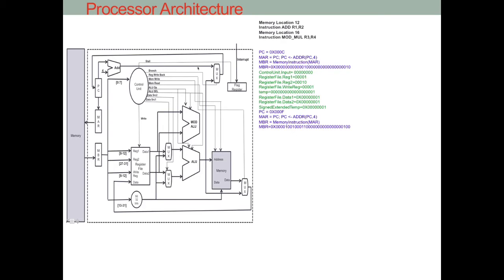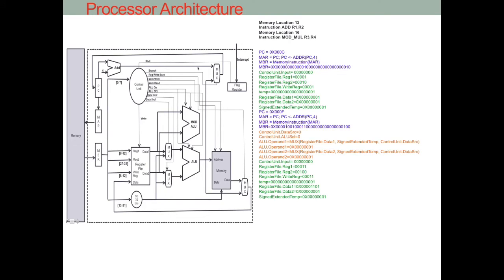In the execution stage of the first instruction, the second instruction will be decoded in the same way. The output from the decode stage will be given as the input to the execution unit, which goes through the muxes, depending on the signal from the control unit, to select which data will be forwarded to the ALU. After the data is forwarded to the ALU, the ALU operation signal from the control unit will be given to the ALU and the desired operation will be performed on the operands.